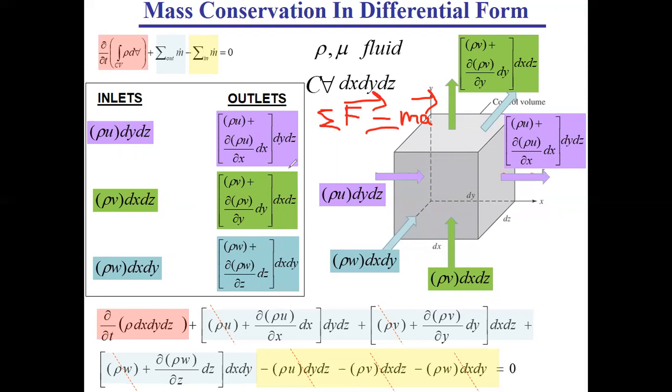That is, body forces, surface forces, pressure forces. Sometimes I can include electrostatic and magnetic forces, etc. So you will see that in ANSYS Fluent, when you want to implement forces, you have all options: electrostatic, magnetic, body forces, etc. Now, for this analysis, when we develop the Navier-Stokes equation, we consider that the dominant forces are body forces like weight.